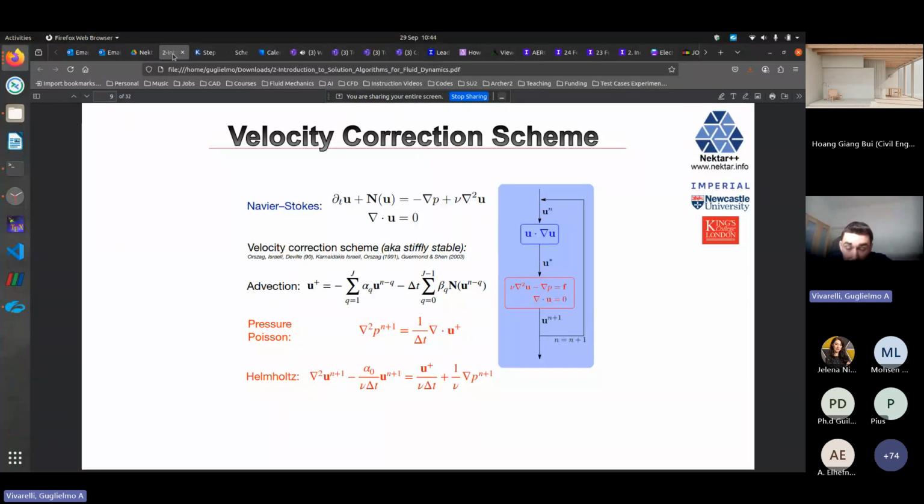On the right-hand side, you've got how every time step works. You first deal with your nonlinear terms in an explicit fashion, and then you determine this intermediate flow field state of the velocity vector, and then you plug this into the pressure equation and the Helmholtz problem and solve an implicit time-wise discretization, and then you move on to the next time step.